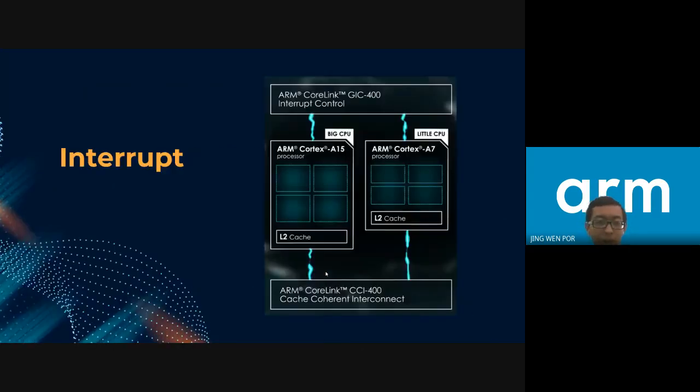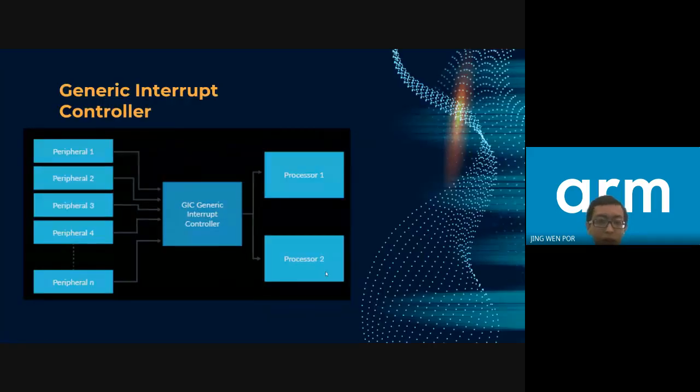As mentioned just now, the interrupt system is controlled by the generic interrupt controller of the processor. The ARM generic interrupt controller is a block of interrupt priorities that carries out interrupt management, prioritization, and routing to boost the efficiency of the processor, and supports the virtualization of interrupts. The ARM GIC has evolved from version 1 to the latest version, known as GIC 4, which, as mentioned, is implemented in the Exynos 2100.